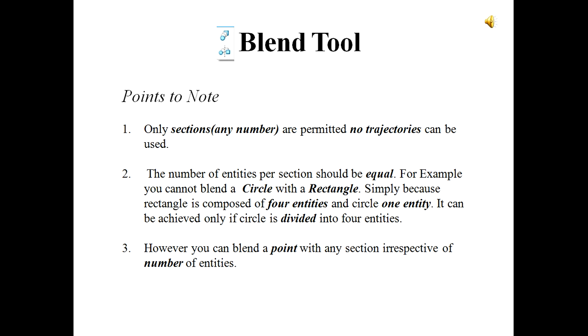The exception to this rule is, however, that you can blend a point with any section irrespective of the number of entities. So with this prior knowledge, let us see some tutorials and exercises of the blend.